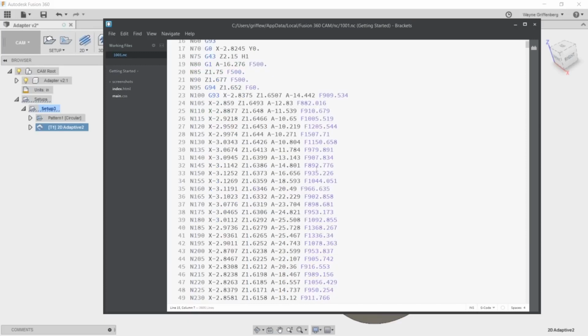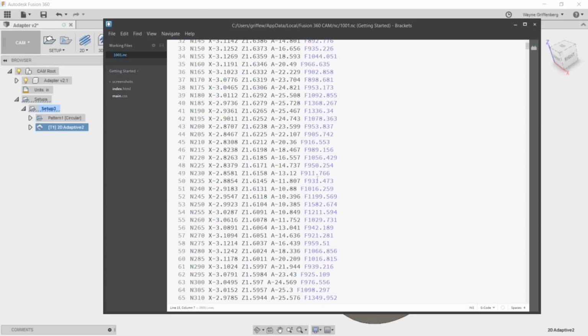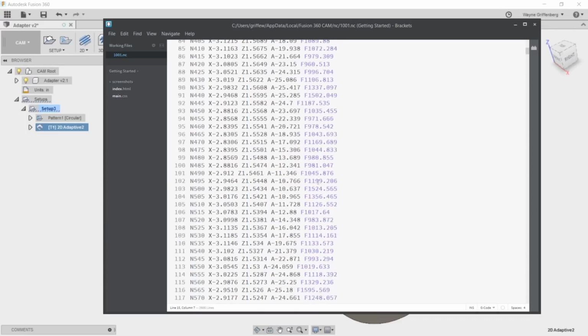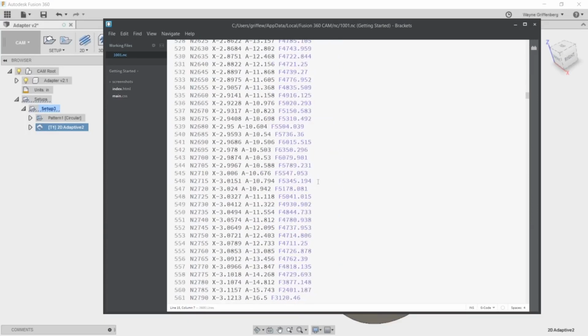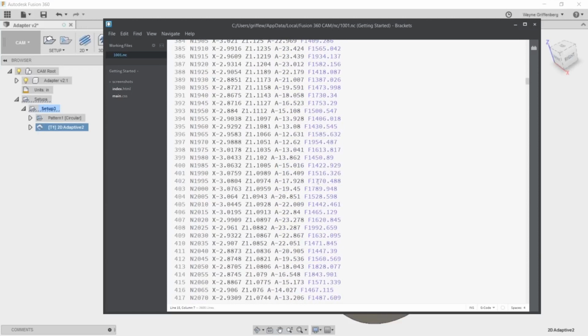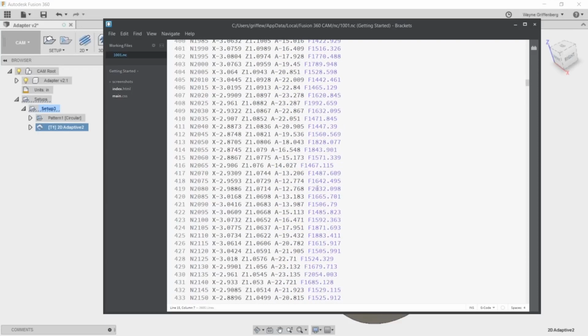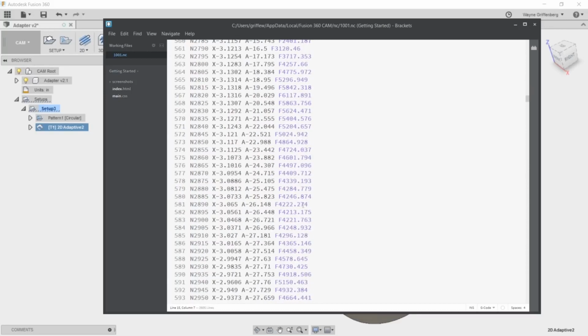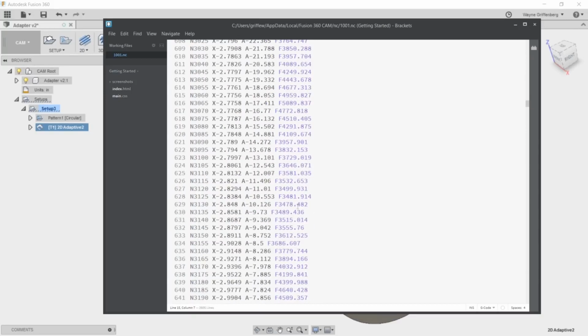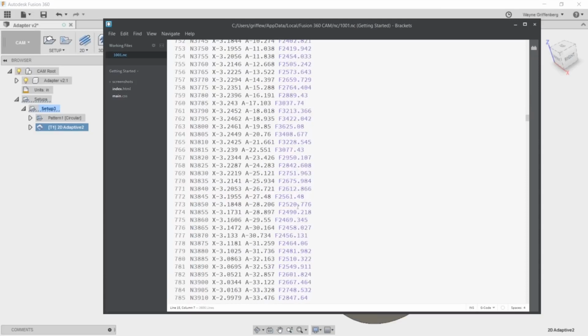And it's updating the feed rates to keep that same engagement the entire time. So as it goes down, this is just helixing into the pocket. And again, you can always change your tolerance to make sure you're getting the optimal load. And down here, as it's in the pocket, you see that X and A axis motion. So you're getting simultaneous rotary and linear motion.